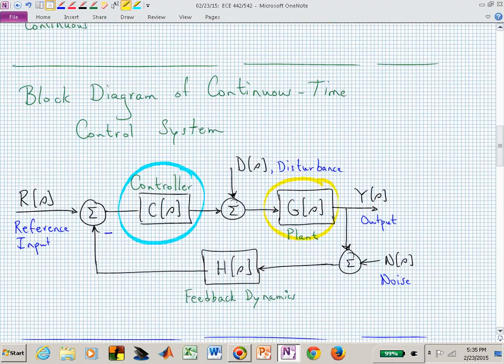The reason we're doing that, again, might be because somebody's already designed an analog controller for an analog plant and they want to implement it digitally. You're in the blue highlighted scenario. You're wanting to replace C(s) with a C(z). Or maybe they want to do the design and the implementation with a digital controller, and they want to discretize the plant, make the G(s) a G(z), and that's what I'm indicating in yellow.